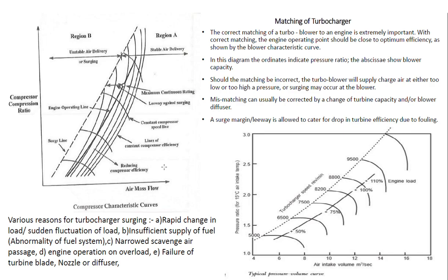Surging is nothing but when a breakdown of airflow takes place in the turbocharger, a reversal of scavenging air occurs through the diffuser and impeller blades into the blower side, which causes surging. So this is the reason for surging.